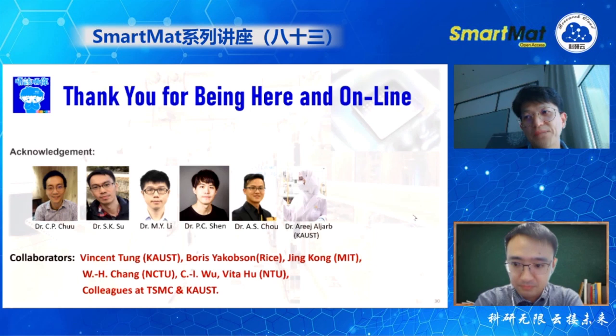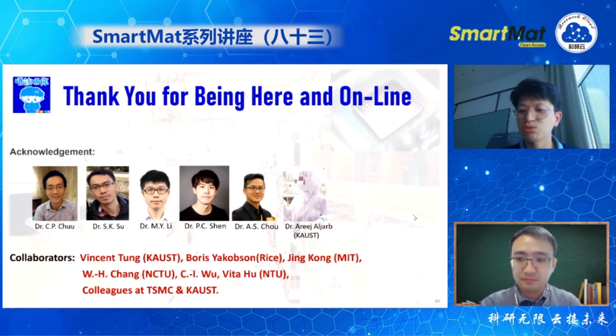You can demonstrate one device, but industry criteria are very different. We always need to think about device-to-device variation. For gallium arsenide, one of the detrimental factors is that the bandgap is simply too small. When you do the fabrication, the chemistry, the surface, whatever process, it changes the device-to-device variation very significantly, just due to the low energy gap.